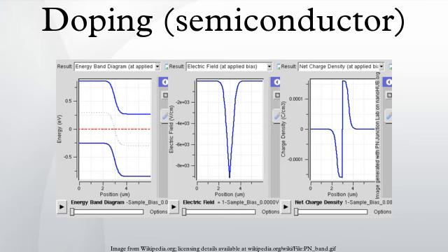Even degenerate levels of doping imply low concentrations of impurities with respect to the base semiconductor. In crystalline intrinsic silicon, there are approximately 5 × 10^22 atoms per cm^3. Doping concentration for silicon semiconductors may range anywhere from 10^13 cm^-3 to 10^18 cm^-3. Doping concentration above about 10^18 cm^-3 is considered degenerate at room temperature. Degenerately doped silicon contains a proportion of impurity to silicon on the order of parts per thousand. This proportion may be reduced to parts per billion in very lightly doped silicon. Typical concentration values fall somewhere in this range and are tailored to produce the desired properties in the device that the semiconductor is intended for.